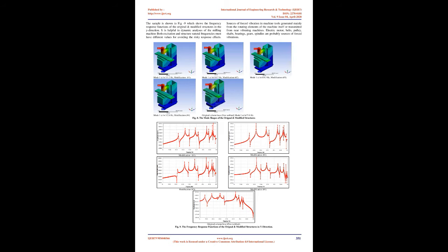Modal analysis is the study of the dynamic properties, mode shapes, natural frequency and damping, of systems in the frequency domain. Structural modal analysis of the milling machine structure uses the overall mass and stiffness of the structure to find the modal parameters. The animated display of the mode shapes of the milling machine column is very beneficial to study and understand the vibration and dynamic behavior.